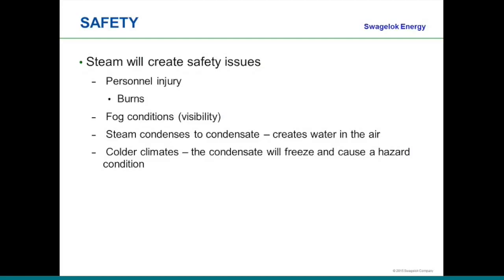Steam leakage will create safety issues. You know, people do get burned from steam. You know, condensate dripping down, extremely hot, burning people. These are injuries that over and over people occur in the field. Foggy conditions or fog conditions for visibility. Steam condenses to condensate, creates water in the air. Cooler climates, condensate will freeze and cause hazard conditions, ice buildup. So there's a multitude of safety issues that we have to resolve and not have available to the plant personnel. So steam leakage we must correct.